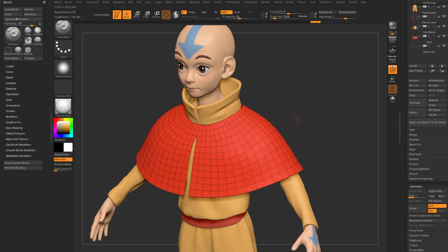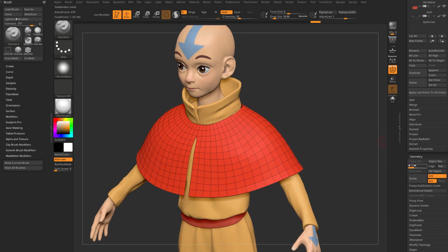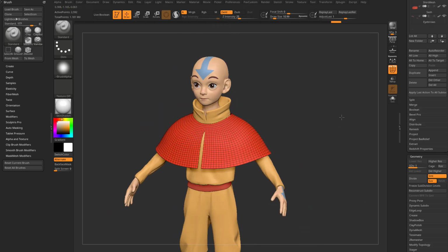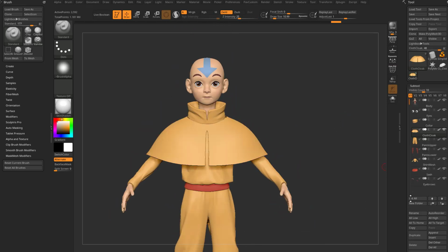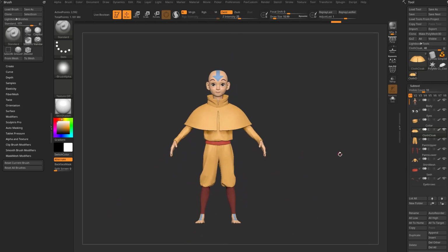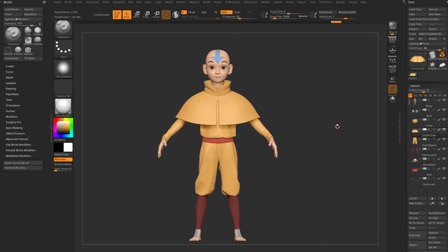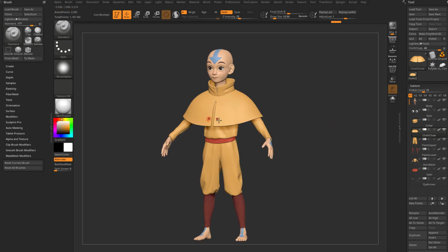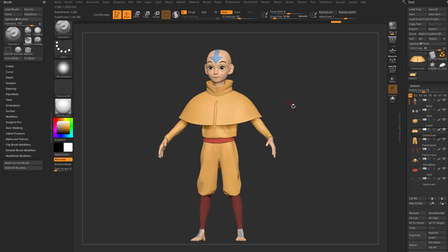If you want to add more wrinkles, what I can do is I'm going to go up to subdivision level 2, and then I'm going to say delete lower. So the exact same setup process we've already gone through, only when I go Z this, it's going to go Z more verts over, and that'll simulate more wrinkles because we have more geometry resolution. But again, the same process still applies. Send over the mesh, create your guides, create your skeleton, bind your weights, turn on cloth physics, bring in your weight map. So we'll go ahead and do that real quick.